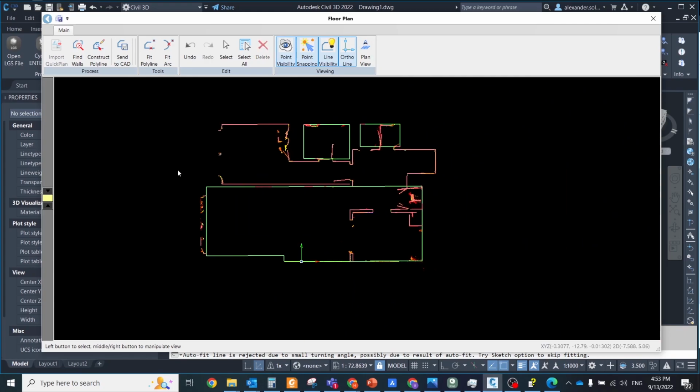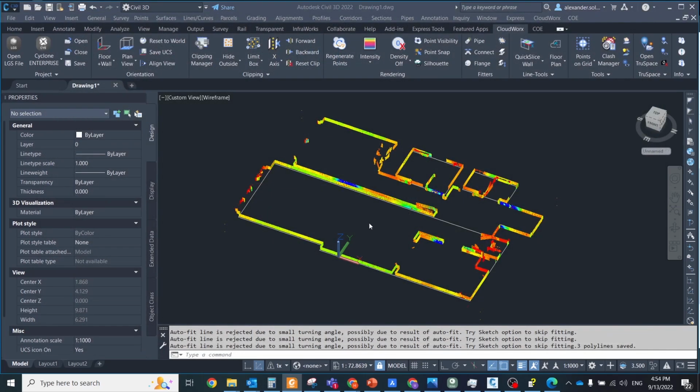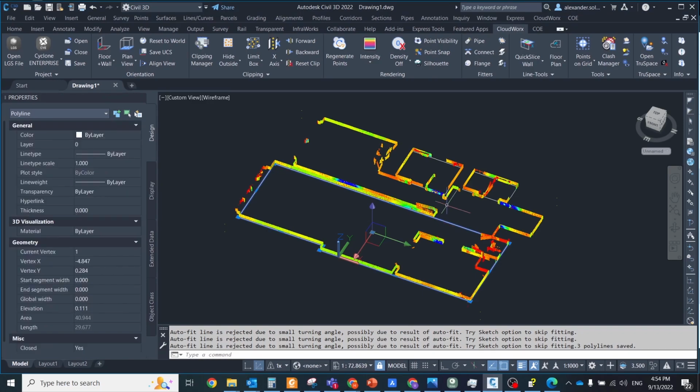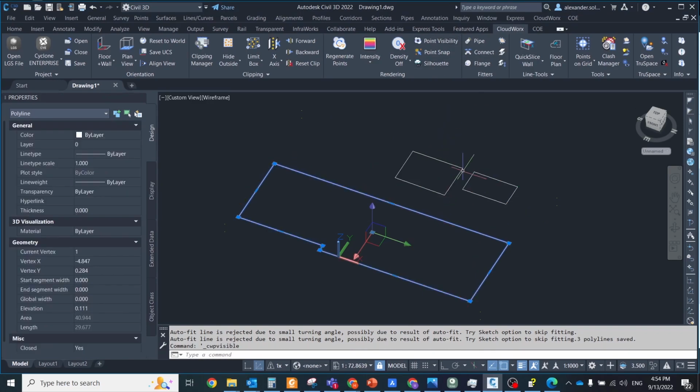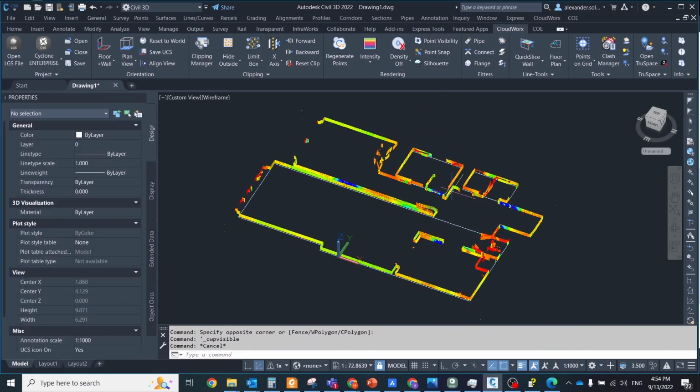Green polylines may be selected and the endpoints can be adjusted to fine-tune your line work or to correct errors. Send to Cut pushes the finished polylines, shown as green lines, back to your current drawn model and closes the tool. Any remaining red line segment will be discarded and ignored.